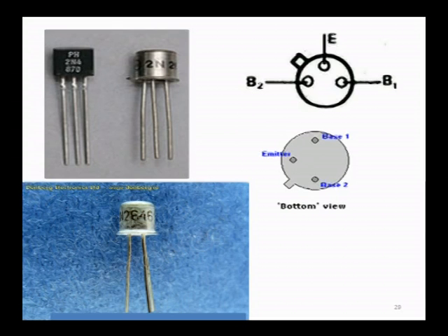Now, there are problems with the RC circuit, because a lot of heating takes place inside, and in fact it can damage your SCR and is not popularly used. And now, the next topic is SCR being fired by UJT. UJT is a unijunction transistor.